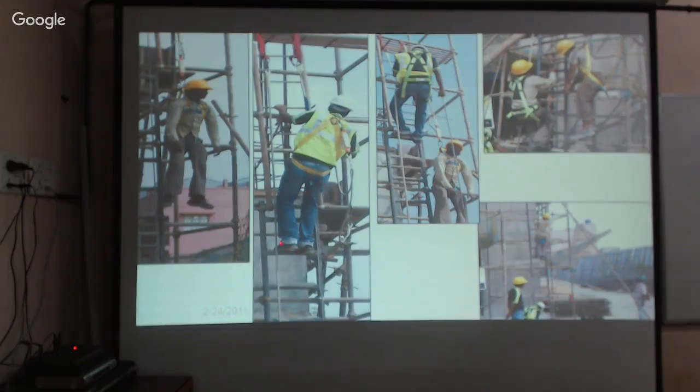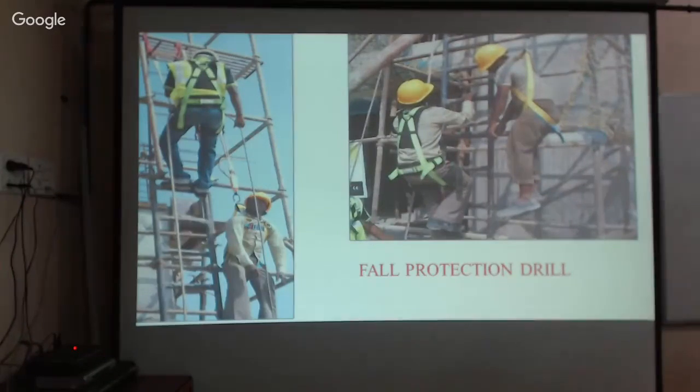I will tell you that safety is compulsory when you are working on the scaffolding. The person must have the safety belt to avoid accidents, and the safety helmet, most important. And the safety jacket, so that everybody can visualize and recognize who that person is.